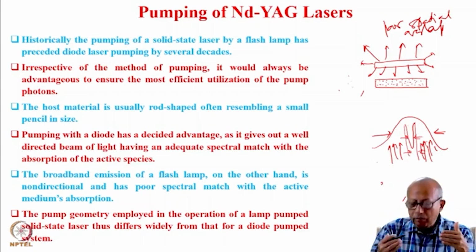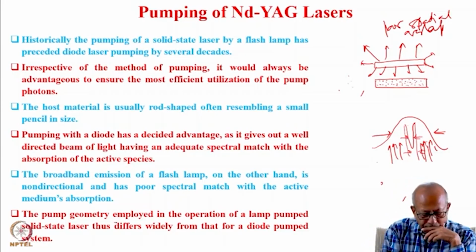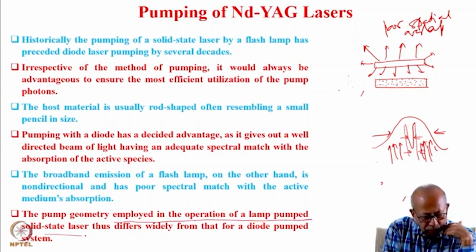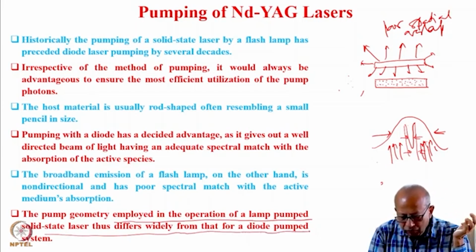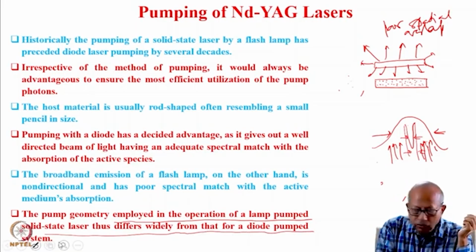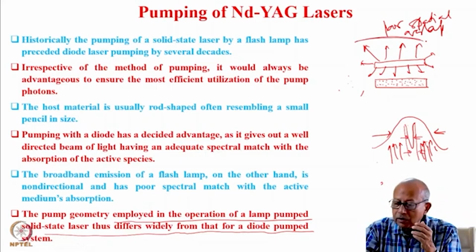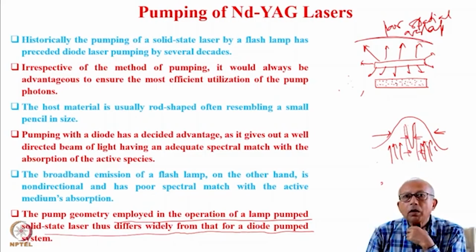Therefore, you can very well appreciate that the pumping geometry employed in the operation of a lamp pumped solid-state laser differs considerably from that for a diode pumped system, because you will have to ensure that you are able to direct all these escaping photons back into the host.